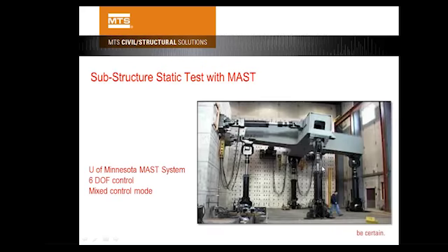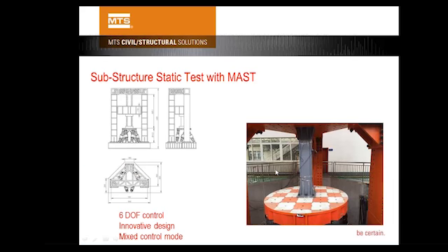So, for example, for this structure, there is a 6 DOF loading system in front of it, and it controls X, Y, Z, and rotation displacements, so that you can control any location in 6 DOF accurately, in force control or displacement control. Then the FEA calculates the command, which can be easily executed through this kind of loading device.